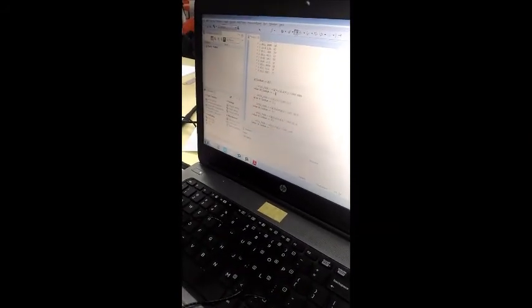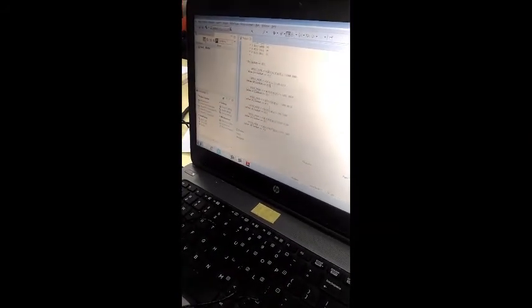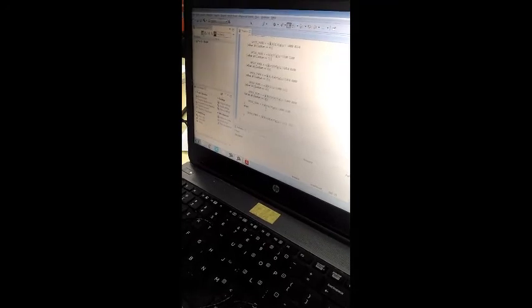With that, I control 0, 1, 2 until 9. Because it's a 4-bit input, after 9 we have 10, 11 until 15. So otherwise I will turn all of them off by providing ones to all the pins. That's all from the coding.